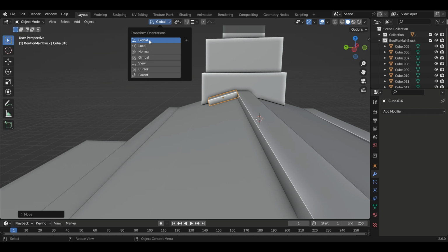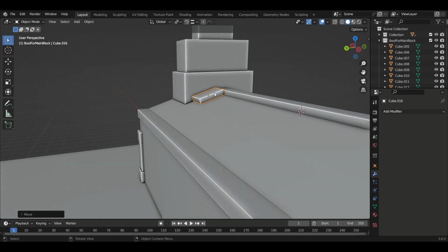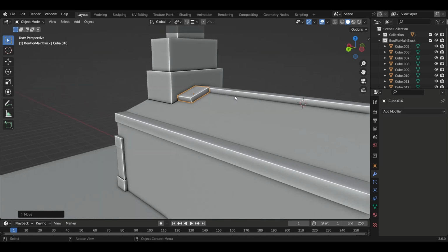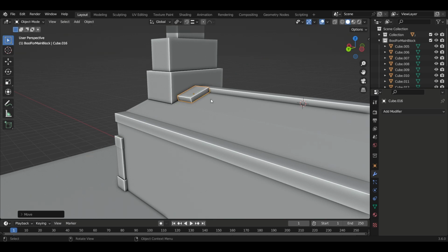Okay, either you can use this option or you can hit Z double time. It is applicable for all the directions, not only for the Z direction. For example, if I'm grabbing it in X direction, actually X direction won't make much difference because there is only change in Y direction and Z direction. X direction will be the same for both. Grab it X once, X twice, there is no difference. Grab it in Y direction, Y once, Y twice. I hope you are getting my point.